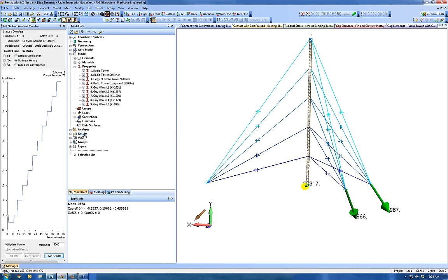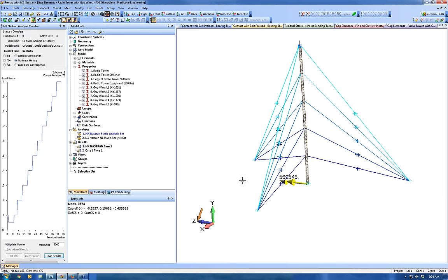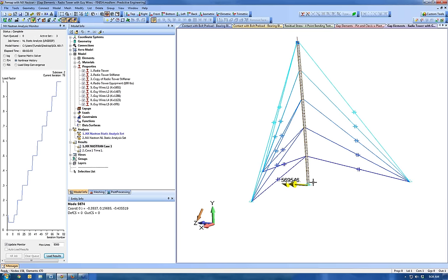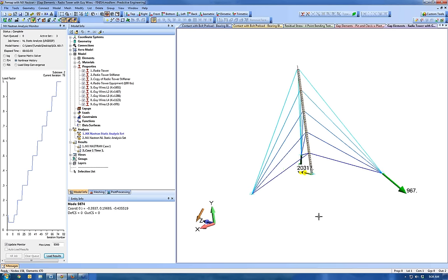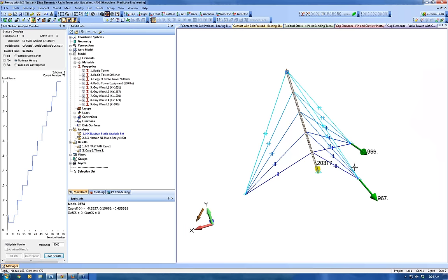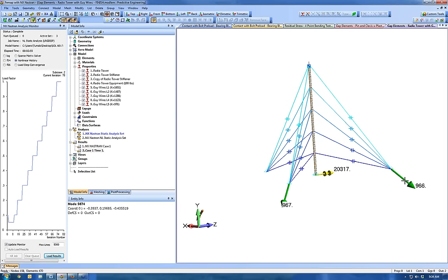And I compared linear and nonlinear runs. The linear run here, this was before I had incorporated the guy wires. You can see massive bending moment at the base, just effectively a cantilever beam there. Once I incorporate the guy wires, my bending moment drops like crazy. I get big tensile reactive forces at these two. You can see the direction of the load. And I get nothing at this one. They're going into compression. They're effectively going slack and not carrying any load. So again, the usefulness of free body diagrams comes through to help you debug the model.